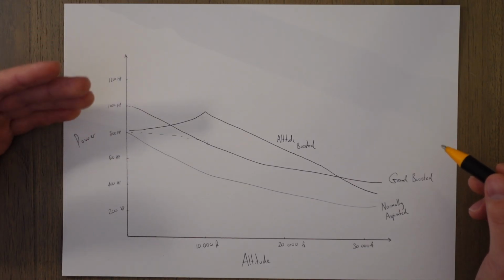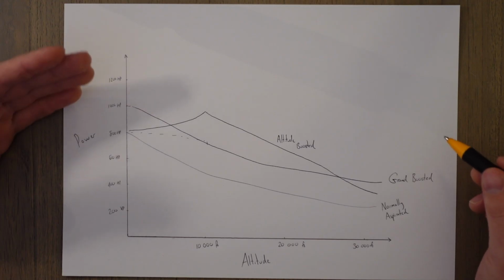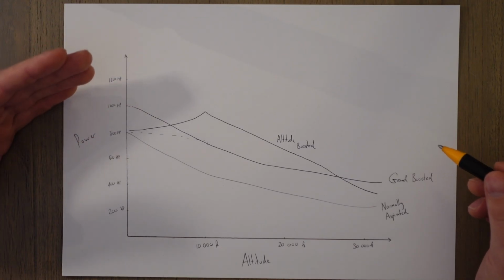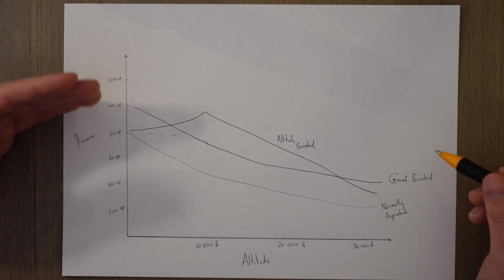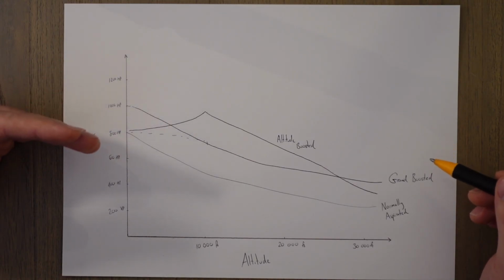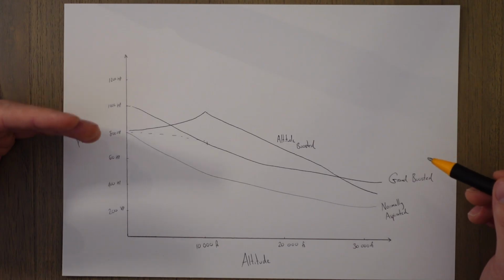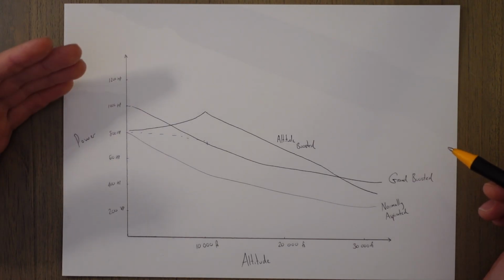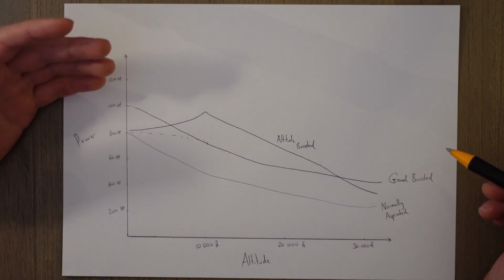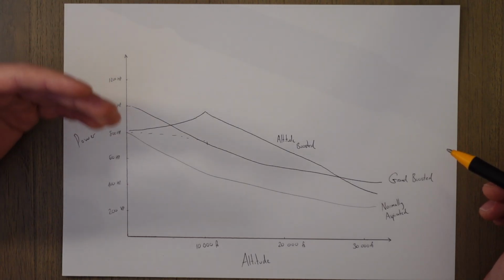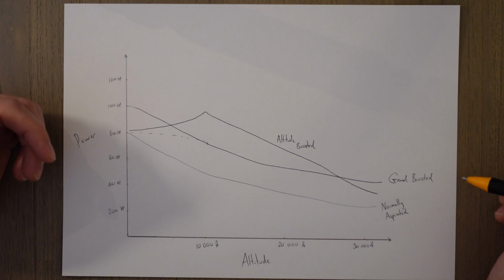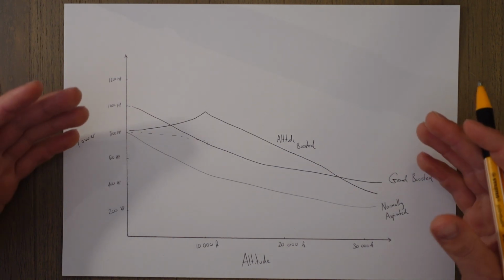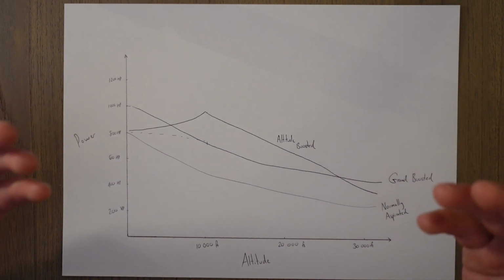This may provide more power than necessary for that altitude, RPM, etc., than in a normally aspirated engine, which therefore allows lower power settings to be used, which can help with fuel burn and engine wear. If we can run an engine at 80% of its max output rather than 100%, then it's going to be good for the engine through the use of an altitude boosted supercharger. So that's what a supercharger is used for, but how does it work?